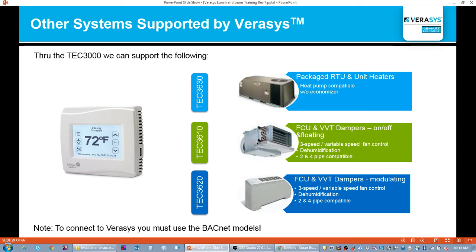They can connect package units and unit heaters. We can also do fan coil units and VVT dampers, or what I like to call zone alone. I'll talk about zone alone in a second, but we have options for fan coil units, be they on-off, floating, or modulating fan coil units. Again, these TEC thermostats come in both wired and wireless solutions.